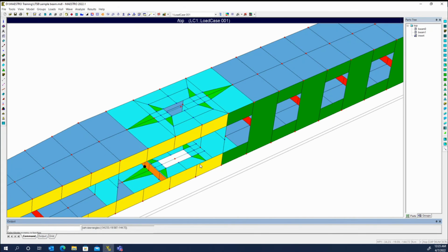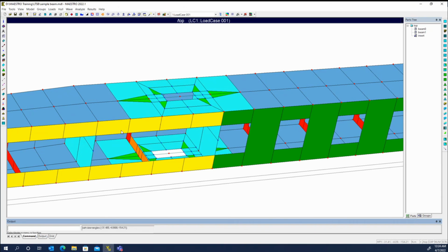Now I rotated the model. Sometimes when you spin the model, because spinning the model is actually executing the set view angles command, I think it disables that merge. So see, it won't let me click on that node, even though it looks like the button is still active, it's not. So I can uncheck it and check it again, and then click and double click to merge the nodes. And now those beams are just fine.